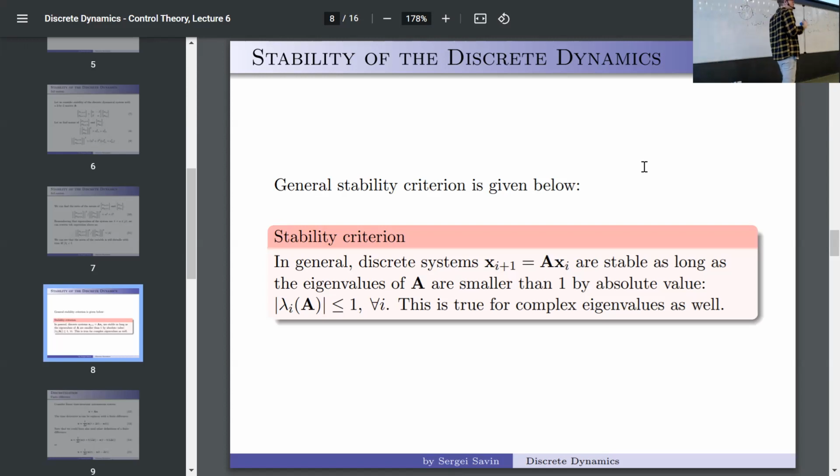So in terms of tools, no difference whatsoever. Just remember what you want to ask. In continuous time, ask for negative eigenvalues. In discrete time, ask for eigenvalues within the unit circle. Okay. So by understanding eigenanalysis, you automatically understand how to design control.